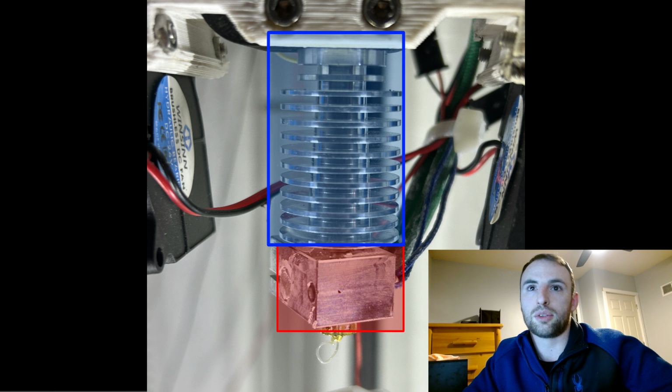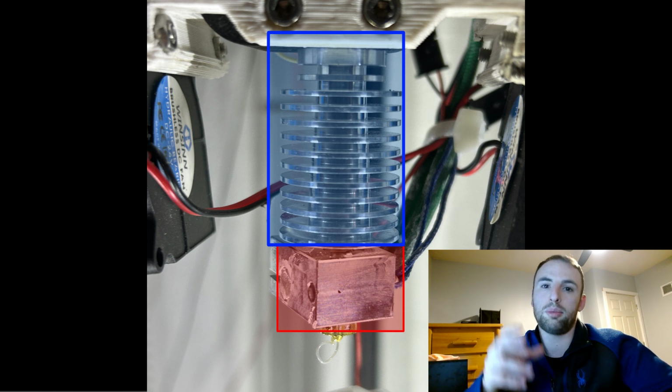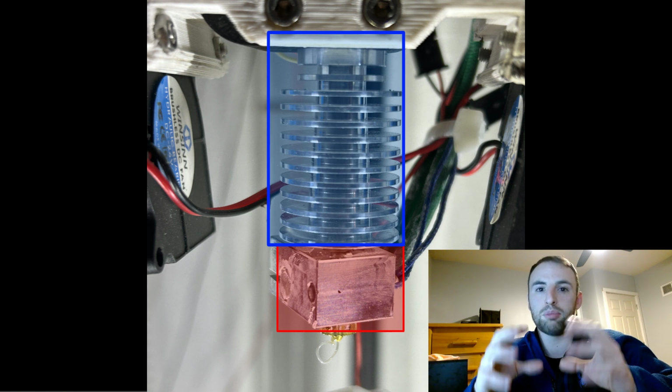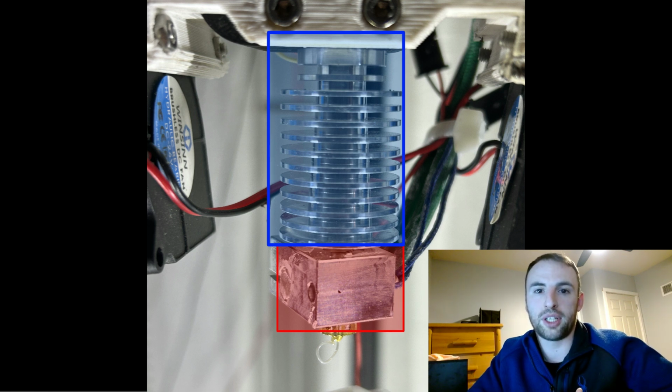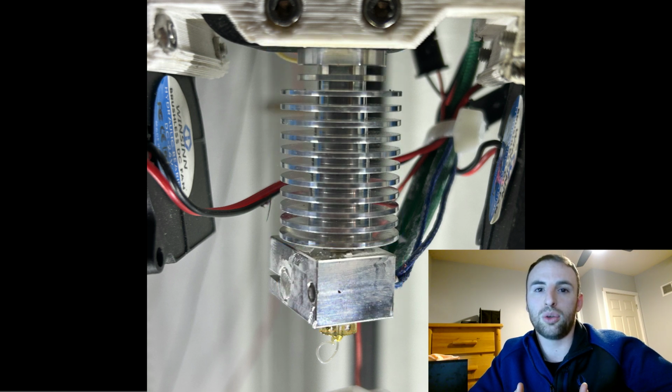And when that heat started to creep up and heat up what was supposed to be the cold section, all the plastic inside there melted. Then when the print head turns off, it re-solidifies and coats all the internal mechanisms and the working gears. So, setting back a little bit, we tore the printer down, we luckily had some spare parts and rebuilt it. And then we got our AI working properly, as you'll see in a moment here.